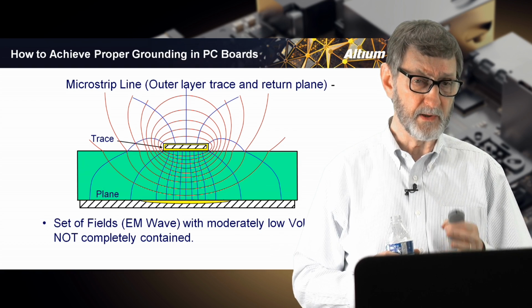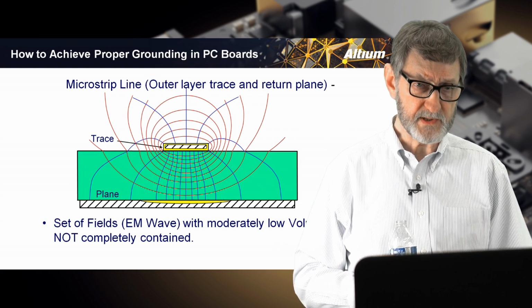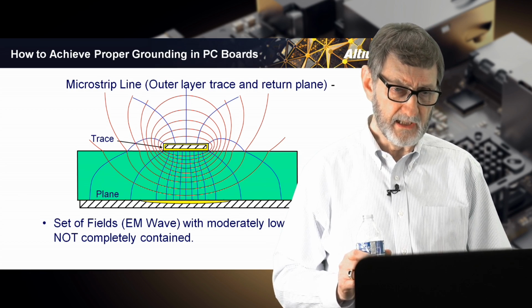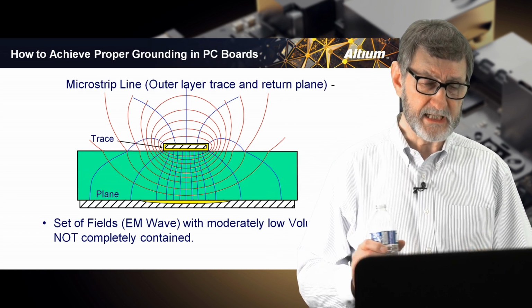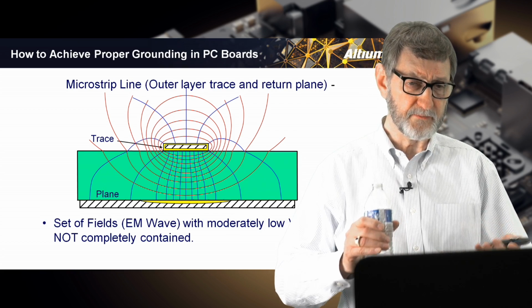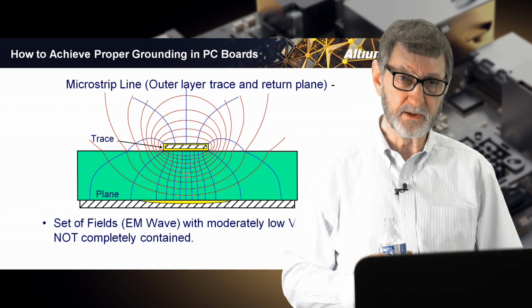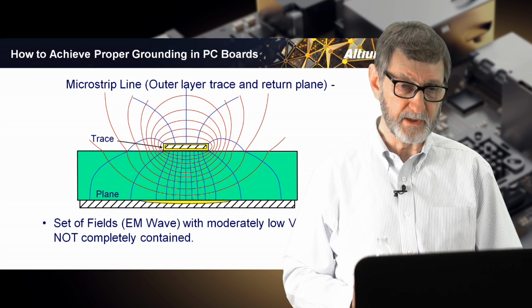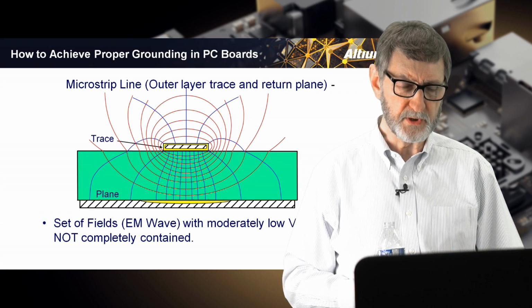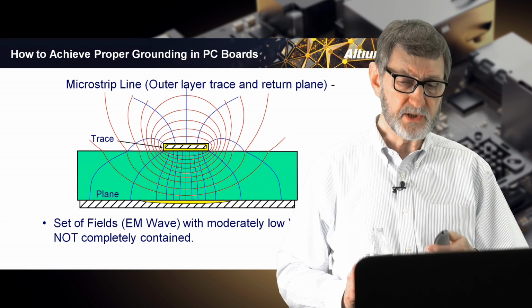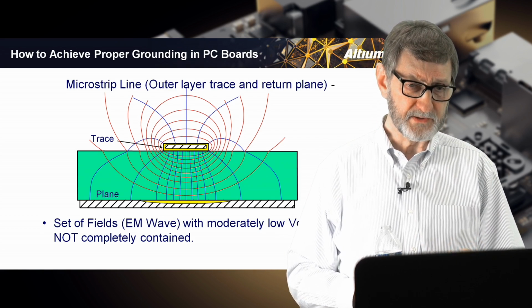On the contrary, though, when you have really short signals that you're only going to route between two devices, a quarter of a millimeter, half a millimeter, and so on, when you're going to route things very short distances, the reality is you want to route them on the outer layer.